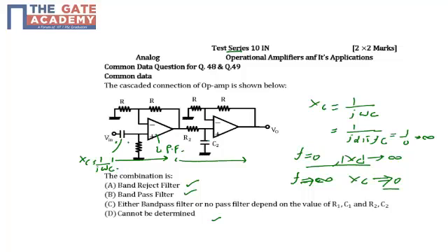It means that this part of the circuit will act like a low pass filter. On the other hand, C2 is again a capacitor and behaves the same. For low frequencies, C2 will act as an open circuit, so the entire signal from the output of the first op amp will be fed into the input of the second op amp. When the frequency increases, C2 will be activated and short circuit this terminal. So the second section acts as a high pass filter.